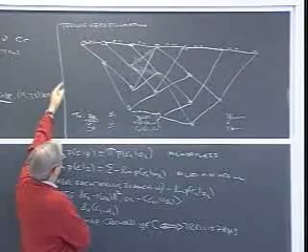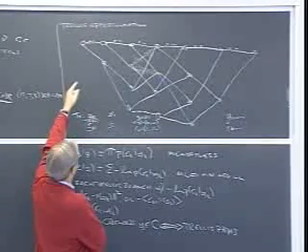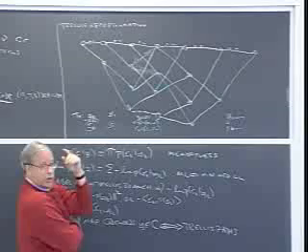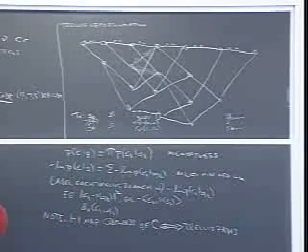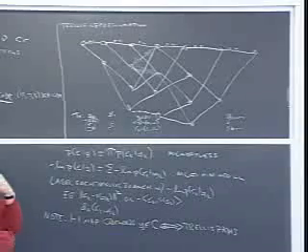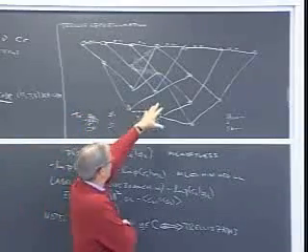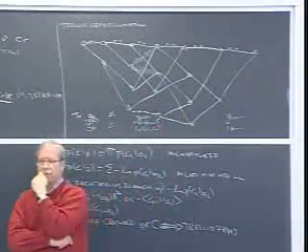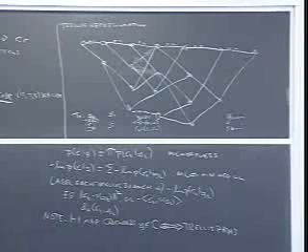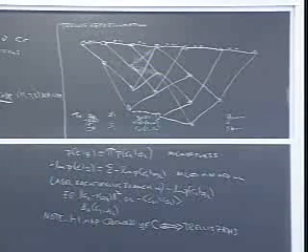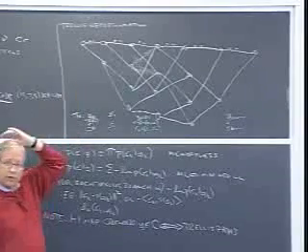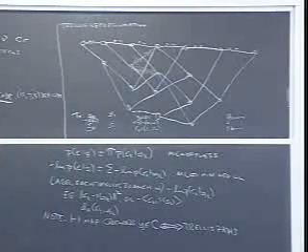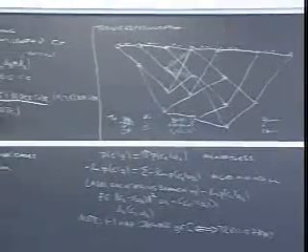Do you see that however I go through the trellis, I'm going to meet 4 two-way branches, according to how there are 4 yes-no questions. It's a binary tree, so there are 16 possible ways to get through this trellis from start to finish, if I view it as a maze problem. I haven't labeled all the branches, but they do correspond to all 16 words in this block code.